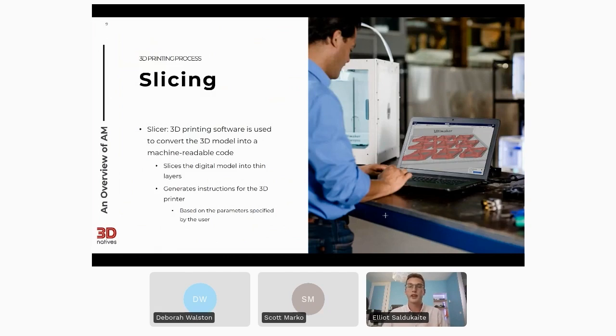So all those settings can be put in the slicer, and then the machine will read those settings from the G-code. So the slicer enables users to convert 3D files into machine-readable and printable files, and also to add their settings, their print settings and material settings, to ensure good 3D printing.